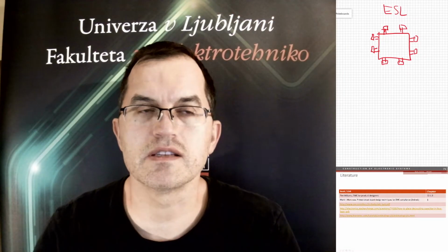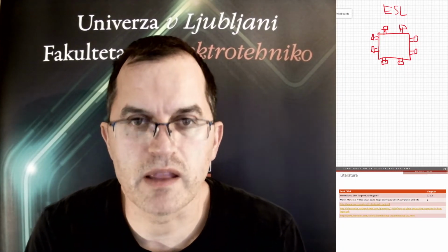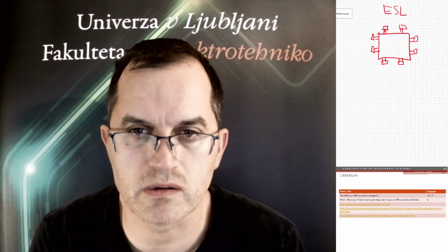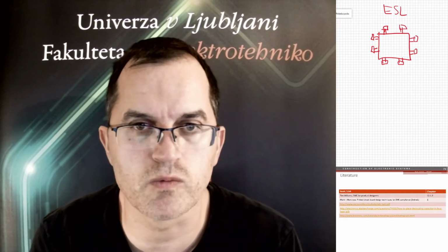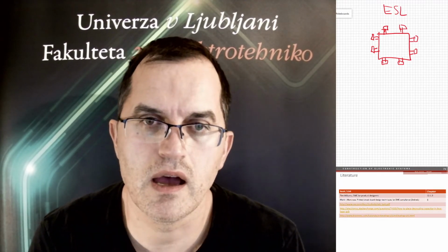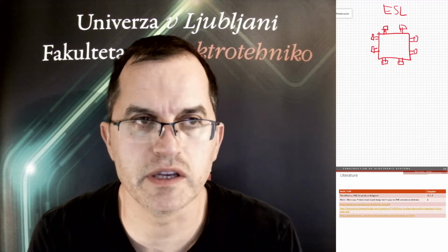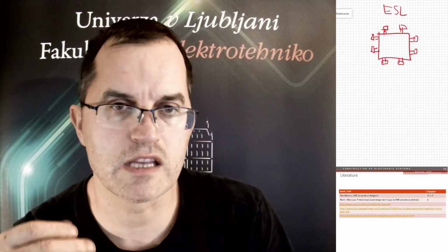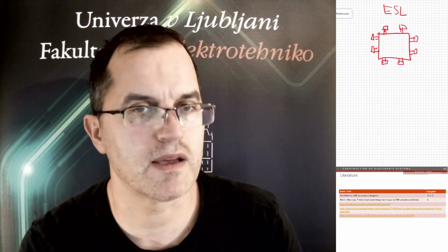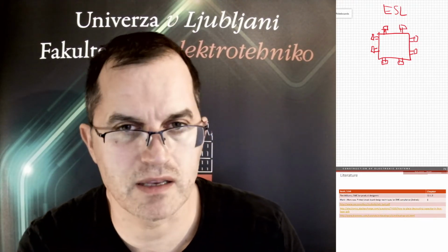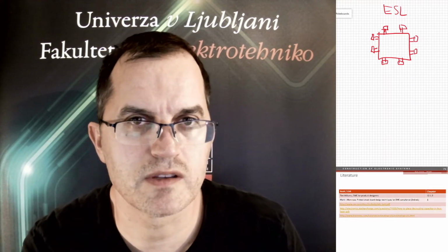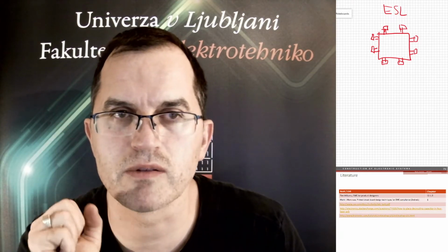So at the end, what can I say? The bypass capacitor placement is one of the main techniques that every electrical engineer who is constructing PCBs should be very well aware of. And it should be like a routine. So the rule is, number one, every integrated circuit, especially the digital ones, requires bypass capacitors. As many of these capacitors as the number of power and ground pins. The pairs of power and ground pins I'm talking about here.